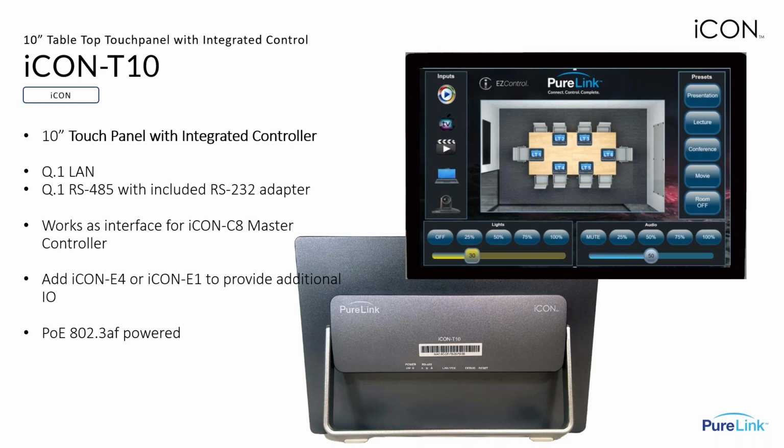Next is the iCON T10. This is the 10-inch touch panel with integrated controller. This is used more on a tabletop. And similar to the T4W, this is the front interface alongside the processor built into the back of it. That includes one LAN port, which powers it on as well via PoE, and an RS-485 port with that RS-232 adapter included.